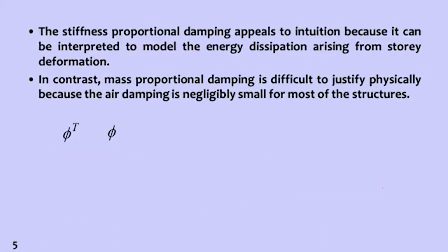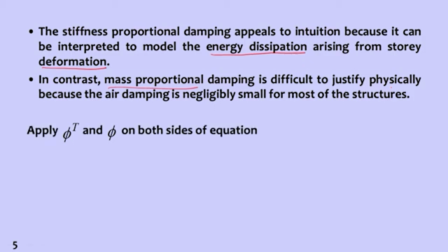Now stiffness proportional damping appeals to intuition. Why? Because it can be interpreted to model the energy dissipation arising from the story deformations. In contrast, mass proportional damping is difficult to justify physically, because as I told you, it is related to air friction. So it is mostly negligible.